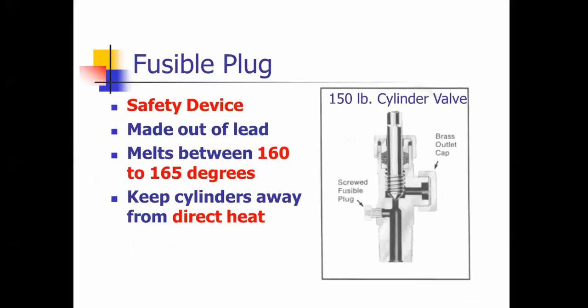Fusible plug. It's a lead plug that's made to melt if the pressures get too high. Like I said, this thing boils at -34 degrees. It melts between 160 to 165 degrees, so there is a test question on that.